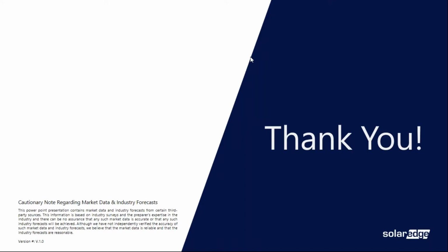Now, if the breakers exceed the 120% rule rating of that panel, then you have to create a generation panel. A generation panel is just another panel, but you put all your generation devices in there. So if you have multiple batteries or another solar inverter, that goes into the generation panel. But again, we still really have to worry about that 120% rule.